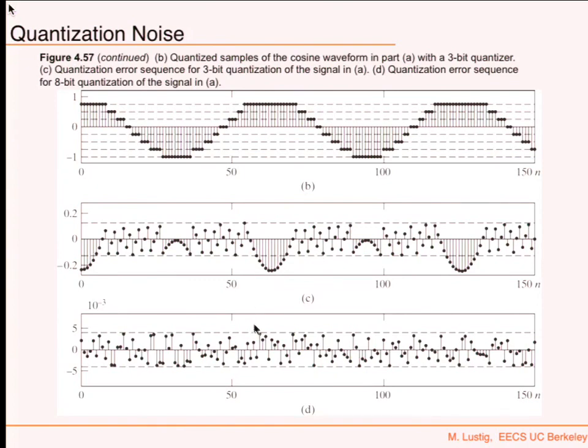But when you quantize to 8 bits, it could look like something random with approximately uniform statistics. If you plot the histogram, it looks pretty much uniform, and not correlated. The autocorrelation of this sequence looks almost like a delta function, which effectively means it's uncorrelated.